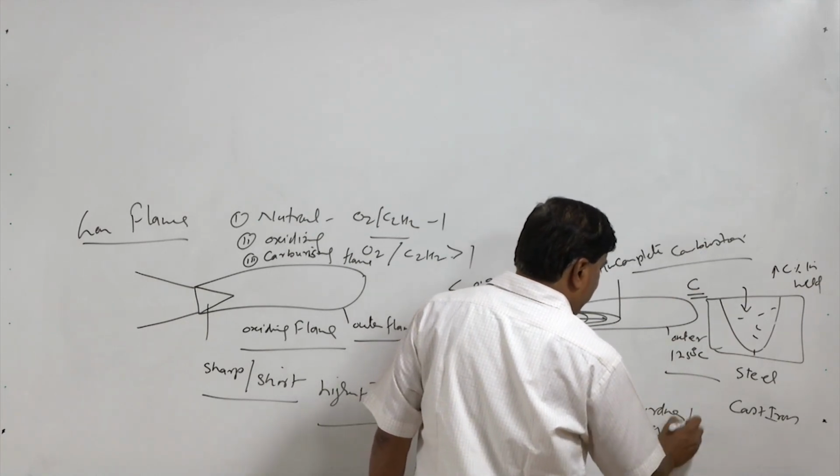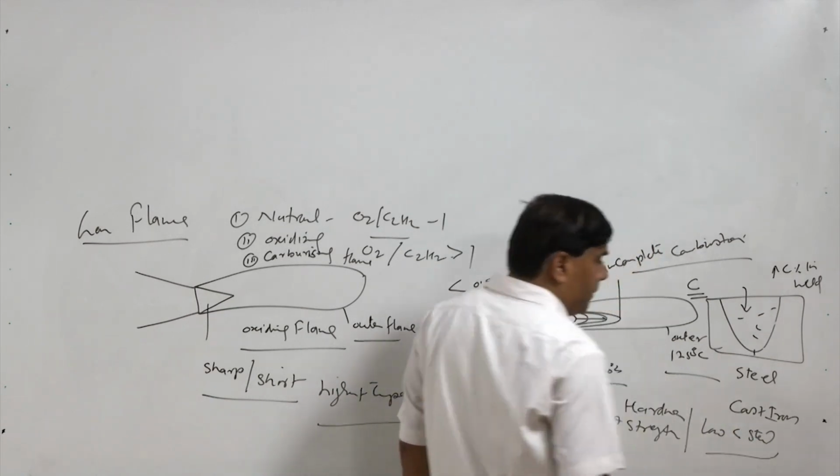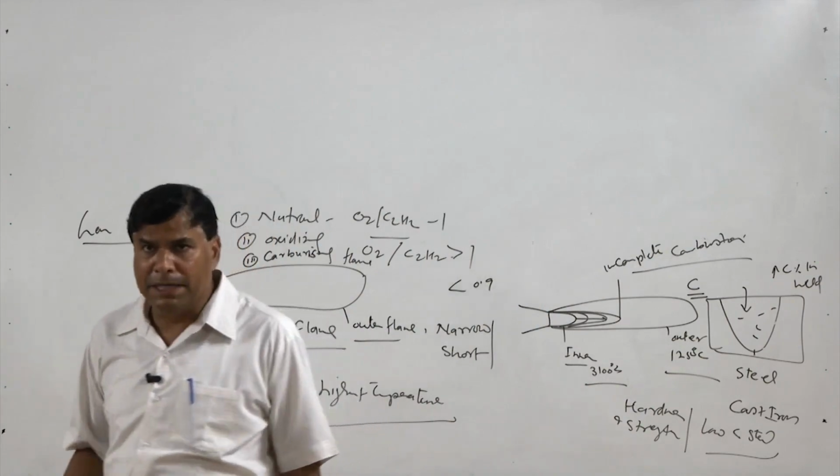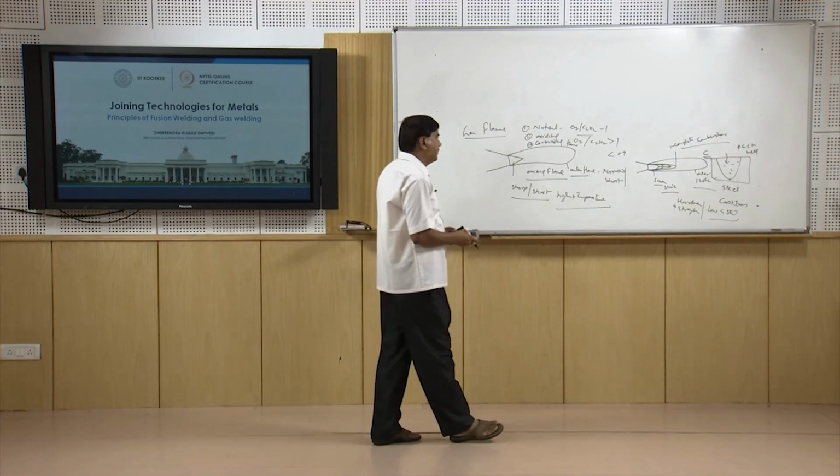This is good for low carbon steels, but in high carbon steels it may lead to embrittlement and cracking of the weld.